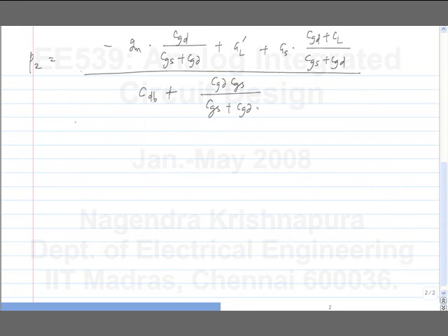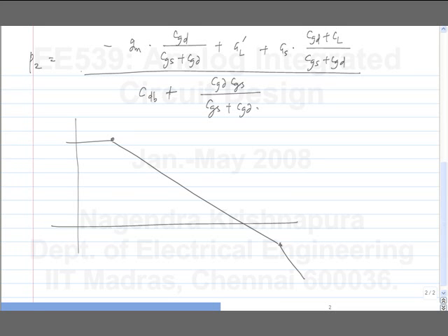If we have a certain DC gain and then beyond the unity gain frequency there are some poles and the dominant pole is here. And this is falling off at minus 20 dB per decade or essentially inversely proportional to frequency. So what is this point? This is equal to ADC times P1. Is this part okay?